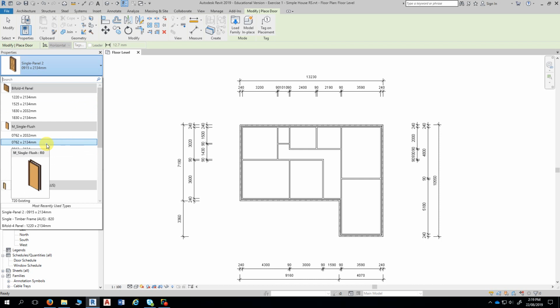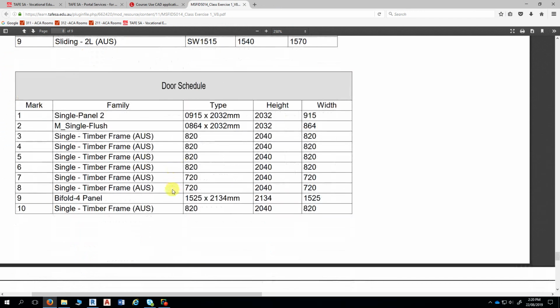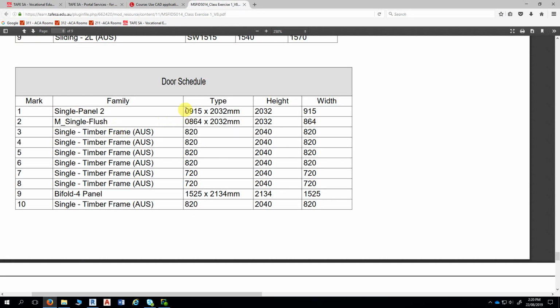Now you can really please yourself. You can add the doors first, or add the windows. It doesn't really matter. With your doors, however, you don't have to create any new types. So there's no new types to create for the doors. You just pick from the sizes that it offers you. All of these types and sizes are standard, so there's no requirement for you to create custom sizes for your doors.